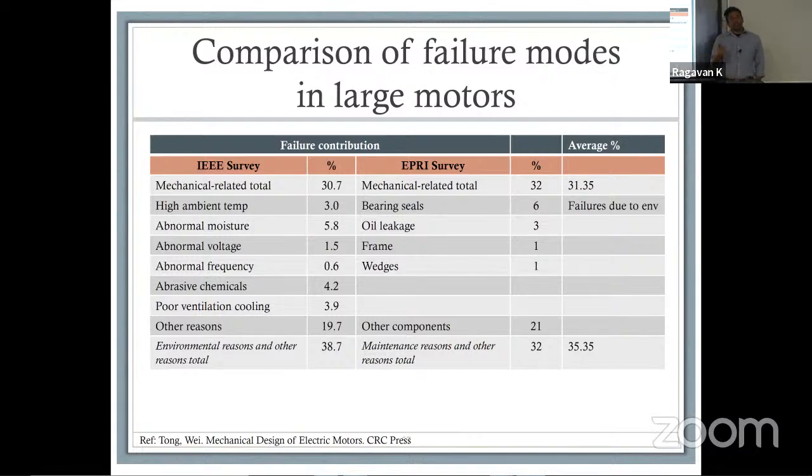Whenever we're designing an electric motor as electrical engineers, we often think about electrical design. We talk about electromagnetic design, right? We don't always think about how we are going to design the overall system. Sometimes you find out the hard way that if you start the design without knowing how thick your housing is going to be, you might end up with a motor that doesn't fit your desired application, because they have volumetric constraints, geometrical constraints. If you design a motor that is bigger than what they need, it won't fit. If it's too small, you might not have the right amount of power.